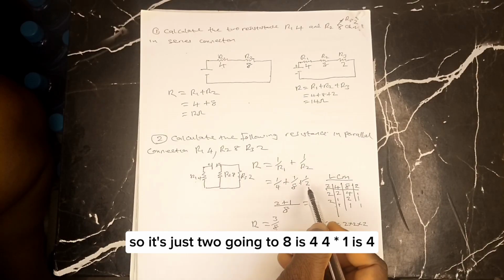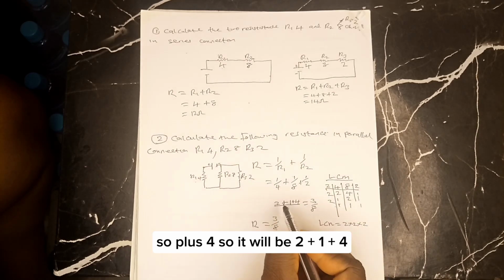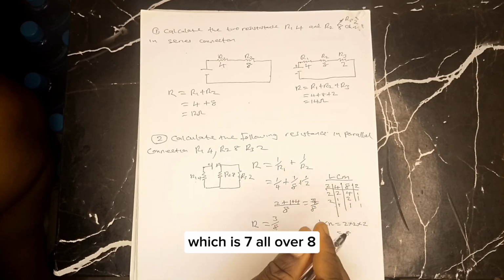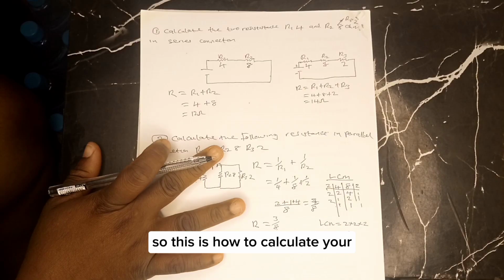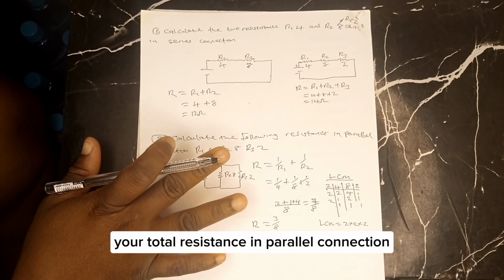So it's just 2 going to 8 is 4. 4 times 1 is 4, so plus 4. So it will be 2 plus 1 plus 4, which is 7 all over 8. And when you use your calculator, you're going to get the answer. So this is how to calculate your total resistance in parallel connection.